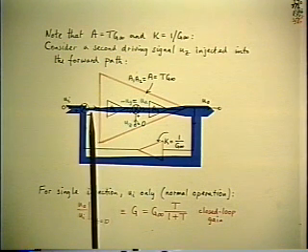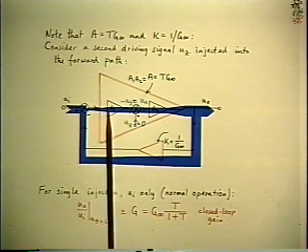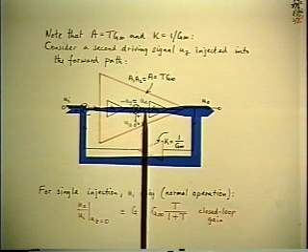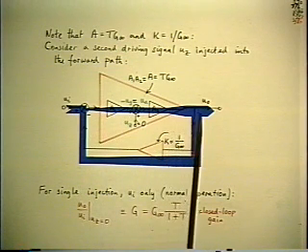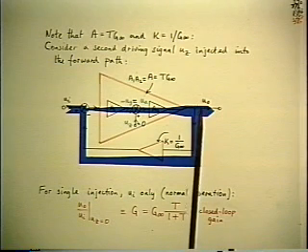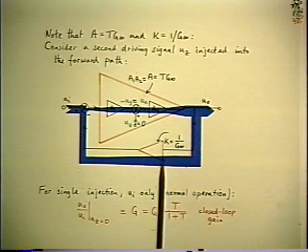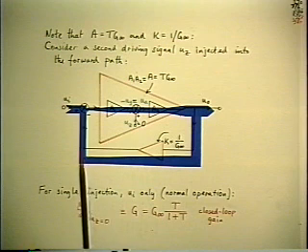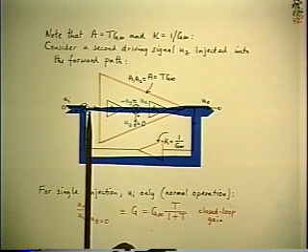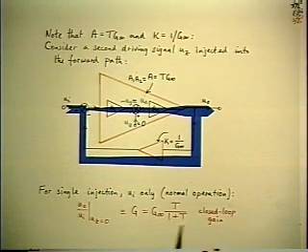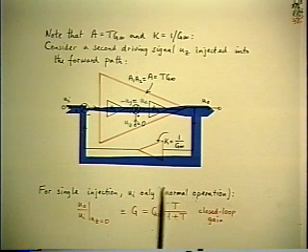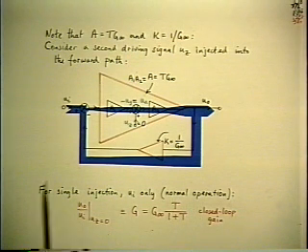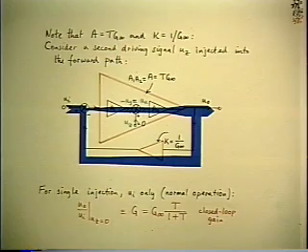So here you have a small error signal which is amplified in A1, goes straight through, gets amplified again in A2, provides the output, and the fed-back signal, which is attenuated and subtracted from the input to give you the small error. So that summarizes normal closed-loop operation with the single input signal UI.